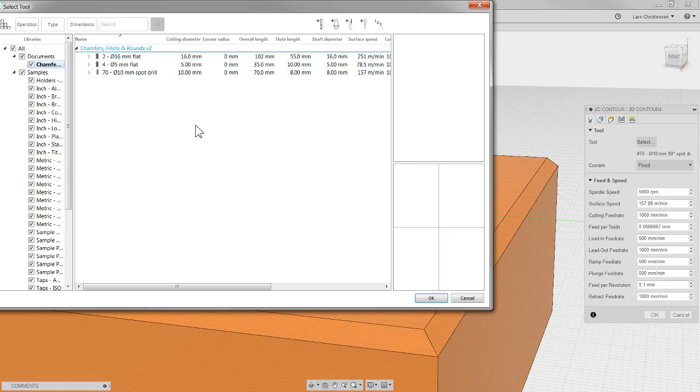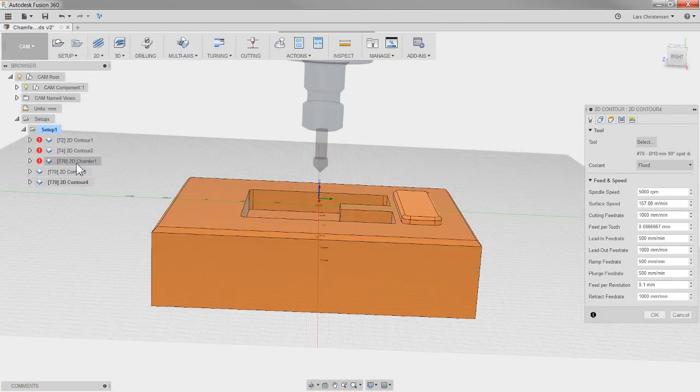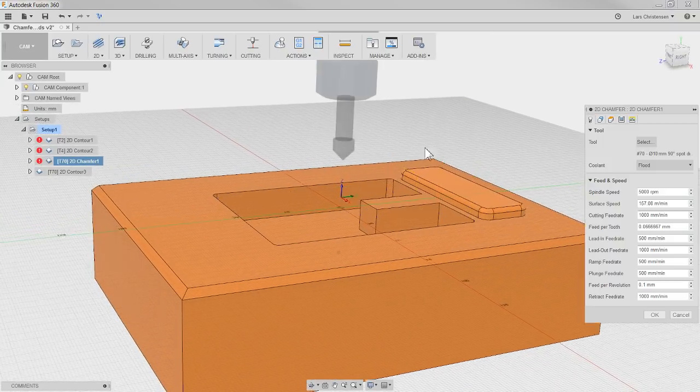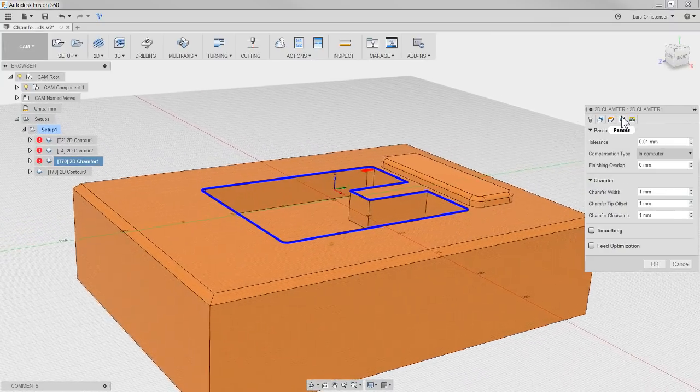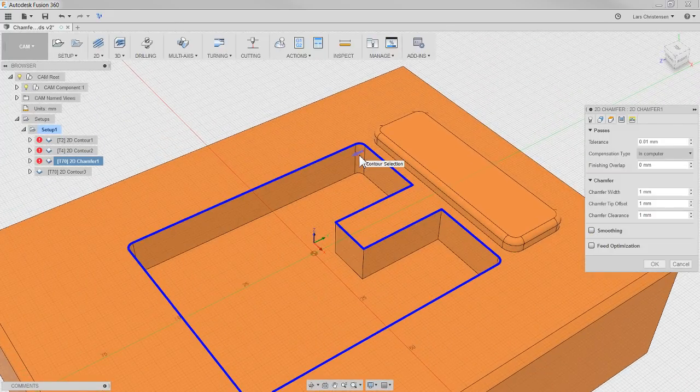When we go in here, you will see. Oh, I can see we got a question. Where are you offsetting the tool for the offset for the tip? That's a great question. So on the chamfer cutter, edit, go to the Passes tab. You can control the compensation just like you can inside the contour.